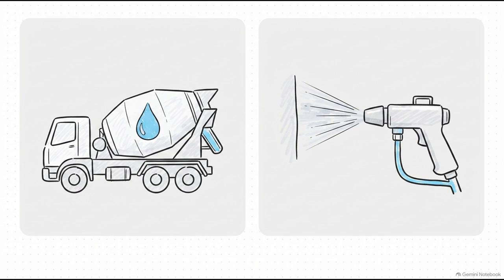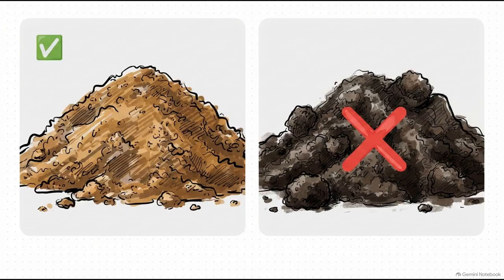But in contrast with dry mix shotcrete, the water is added right at the nozzle. This means the whole operation is highly dependent on the nozzle man's visual control. And this brilliantly illustrates what we mean. In practice, good visual control for dry mix gives you a surface with a nice, moist appearance, but without any excessive wetness. But look at the bad practice.